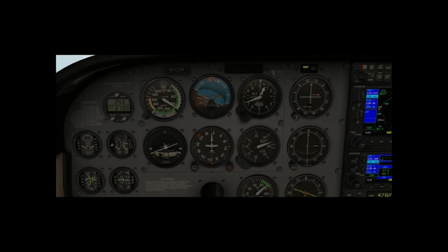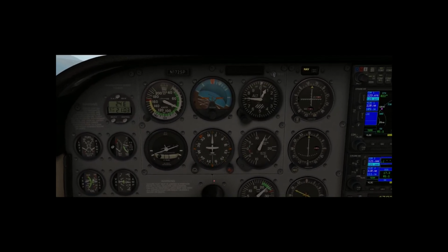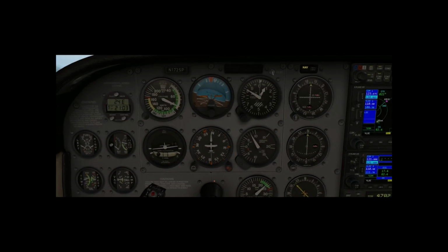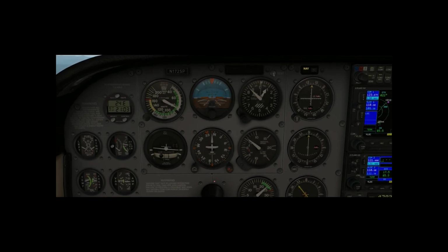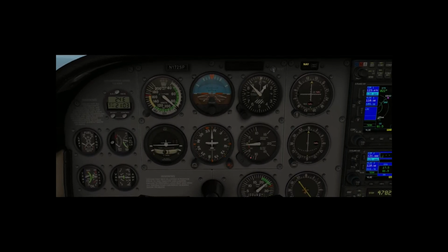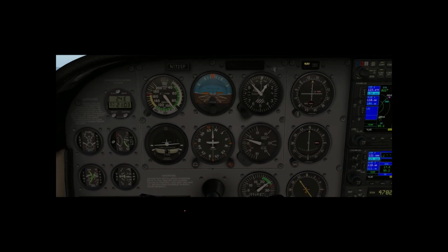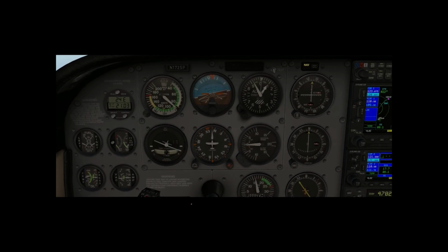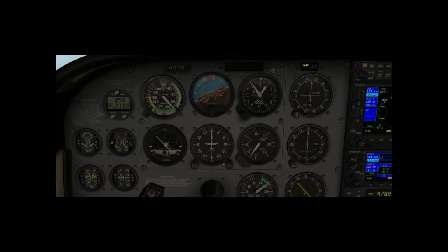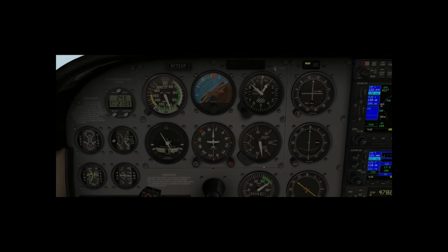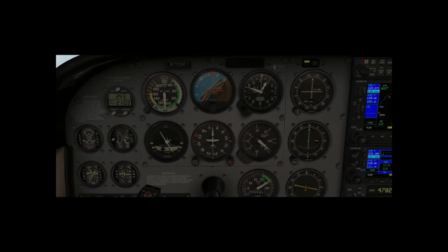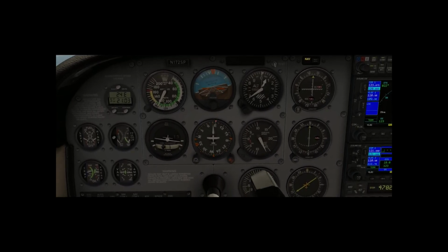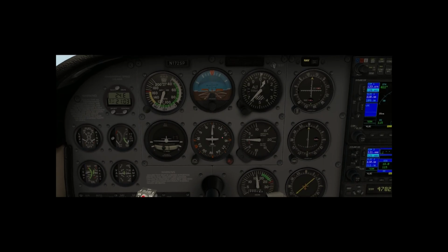Looks like we're in a left turn, uncoordinated. The wings level, now we're descending, slowly becoming coordinated. Airspeed's increasing. Power just went down. Power's up. Vertical speed decreasing. We're in a descent, very steep descent. Nose low. Uncoordinated. Wings level. Nose high.